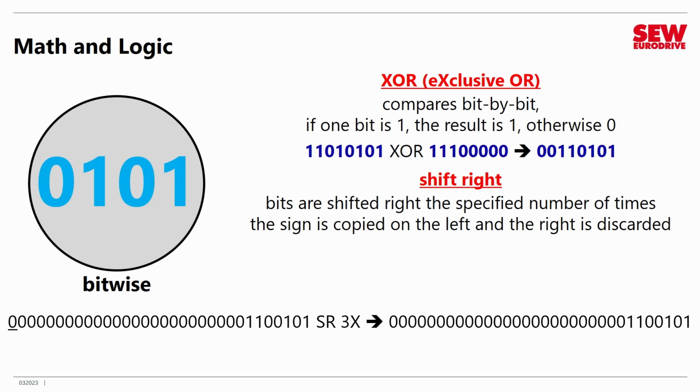So we're going to shift it 3 times, which means that the bits are going to move from left to right. The least significant bit will fall off the table, and the most significant bit, which is the sign bit, will get replicated. So watch it closely as we move the bits. You'll see it happening on the number that's on the right side of the screen. Here we go. Here's our first shift. Notice we duplicate the sign bit, and if you look at the least significant bit end, that's shifted down by 1. Here's another shift. Here's a third shift. You can see those bits have all moved down, and the sign bit's been duplicated 3 times.